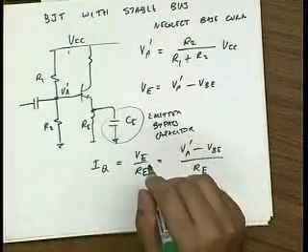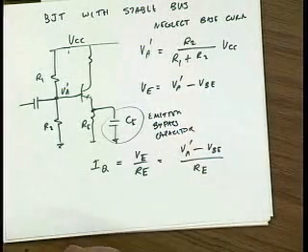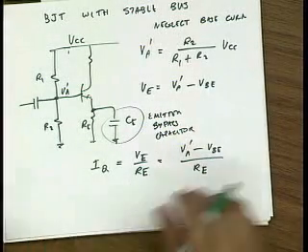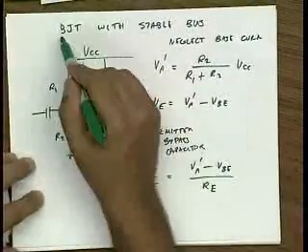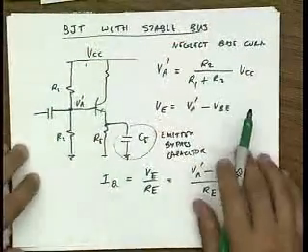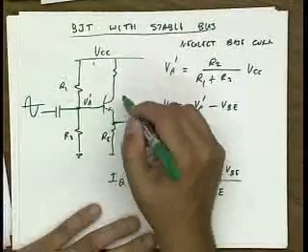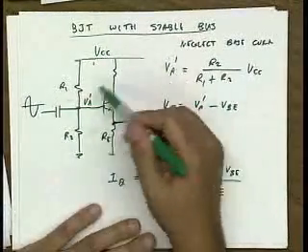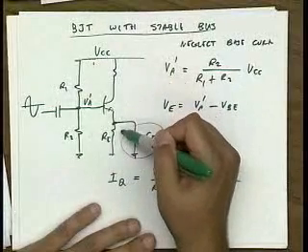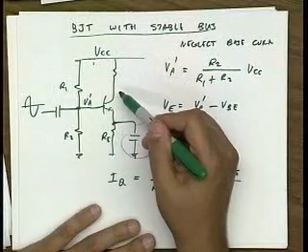Okay. Now the reason why I claim that this circuit has a stable bias is that imagine I bring in a large signal here. This large signal will generate even-order distortion through this nonlinearity, which would tend to increase the DC current, right?